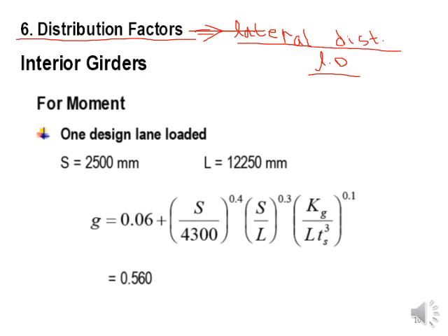For the lateral distribution you need this factor G, the lateral distribution factor, which you multiply with the moving vehicle values to get their effect in the longitudinal direction. So the lateral directional effect has been transferred in the longitudinal direction, and then you place this load longitudinally by multiplying it with G, and calculate the maximum effect for moment and shear by using the ILD.